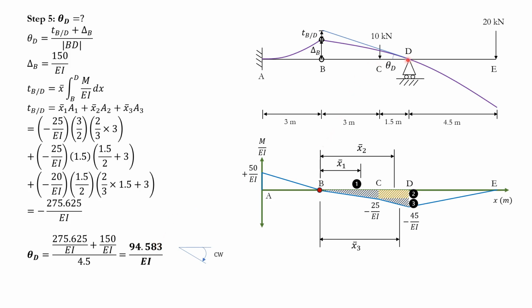You just have to look at the elastic curve. At the end of the day, wherever you doubt any situation, just go to the elastic curve and take a look. This slope is a negative slope. This is positive, this is negative. Counterclockwise, clockwise. Or you can take a look at the beam. So here, this is the horizontal original shape. This is the curved. So as you can see how it's deflecting like that.